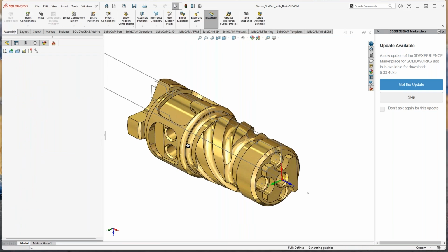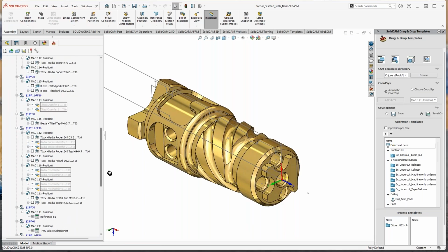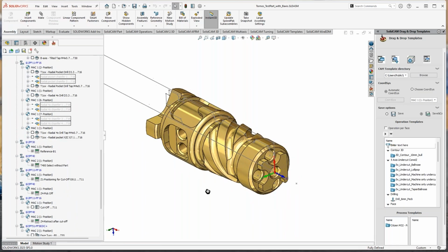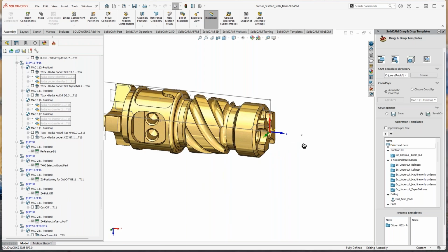And the best way to show you this feature is actually to go into the part transfer routine. And as you probably know, we start on the Swiss type on the main spindle, and then we have a routine where we take the MCO, where we are going to extrude our part to the cutoff location, take the cutoff tool, and pre-position it in Z and X.